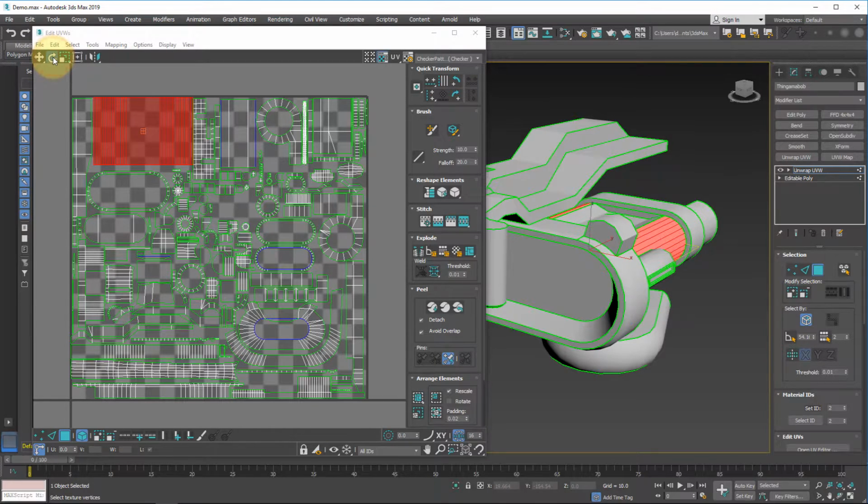Next, of course, is rotation. If we select rotation, it does exactly what we think. It'll even tell us right in the middle how many degrees we're rotating. If we hold down Control, we can actually snap it in 5-degree increments. And if we hold down Alt, we can snap it in 1-degree increments.